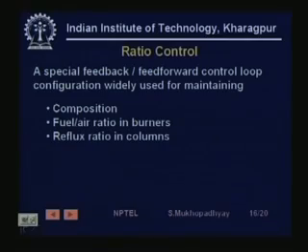Similarly, in distillation columns, reflux ratio is a very important thing which decides product quality. So there are various situations where two materials must be brought together in some reactor or some chamber in precise volumetric flow ratios, right. It is in these situations that you apply ratio control.